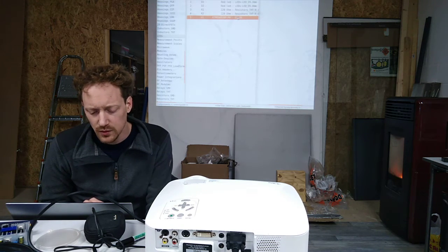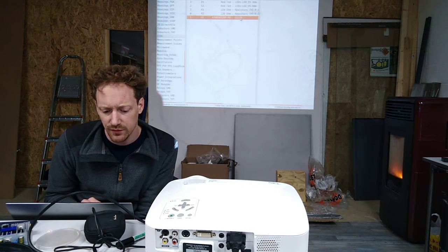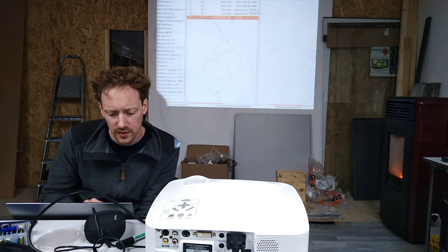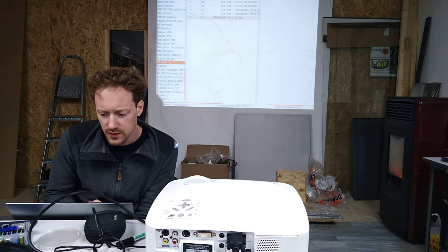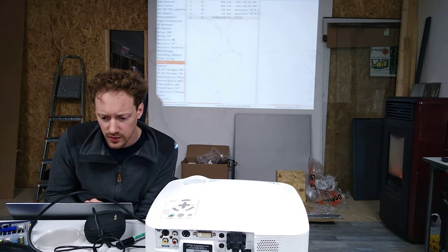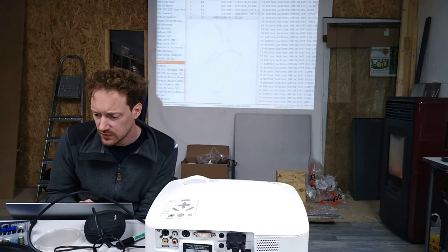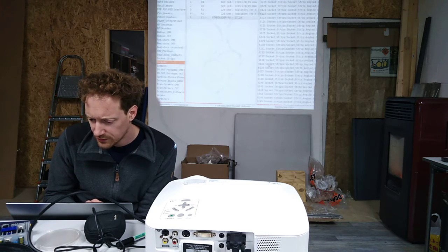And well, it gave us an error that it cannot find the footprint for this one, and I figured this out. So in a new version you have something like that, package, but now we're going to use sockets. And this is where I turned off the filtering. So I think this is just the fact that it's an old version. So I go to sockets. And then we have socket strip.